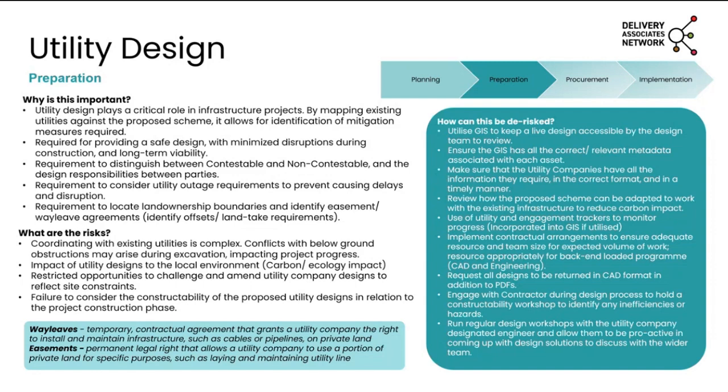So in terms of what the risks are, utilities can be very, very complex. You can have certain areas where there are a lot of utilities, certain amount of unknown utilities. One thing I haven't spoke about is private utilities. So far I've focused on public utilities, which you can obtain records for. There will also in rural areas be private utilities that are owned by the landowner. So you will need to engage with a landowner. They may not have records of those, but they will be able to provide information. So engaging with landowners as well is critical.